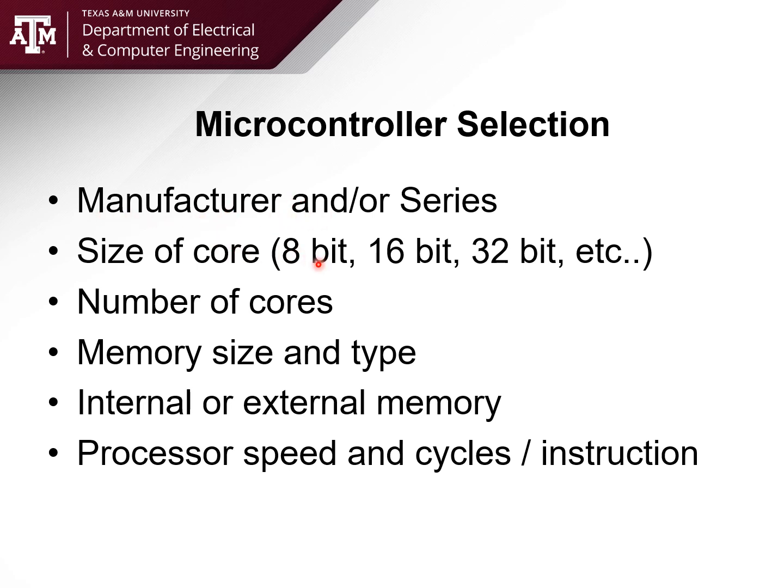The size of the core: 8-bit, 16-bit, 32-bit, 64-bit, etc. This really depends on the technology. If you're coming up with something where all you're doing is controlling a temperature or a valve, turning a heater on and off, for instance, you can probably get by with an 8-bit controller. Something simple. The advantage of the lower bit family is that they're usually more reliable. They're slow, but they're guaranteed to work. So you're going to have more reliability this way.